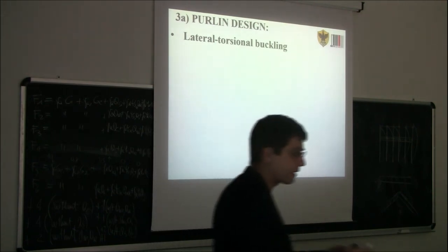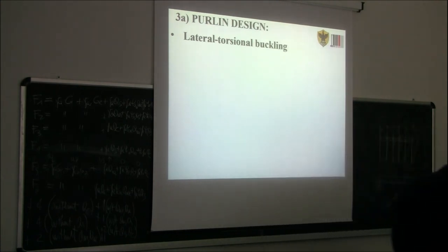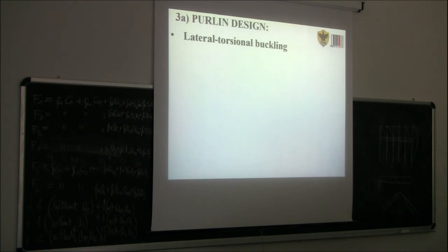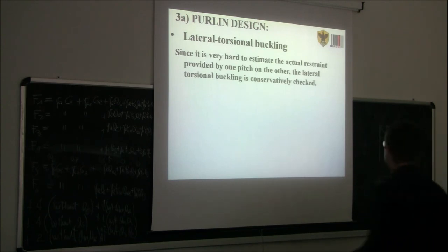Remember, we said before that lateral torsional buckling is a big problem if we have a narrow beam that is very high and long. In this case, we have a kind of squat beam, more or less 14 by 20. And the length is of course important compared to the depth, but again, the depth is not very high. So we can expect less trouble when checking the lateral torsional buckling in this case.